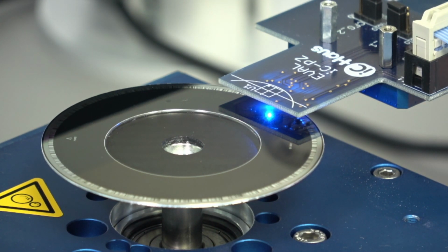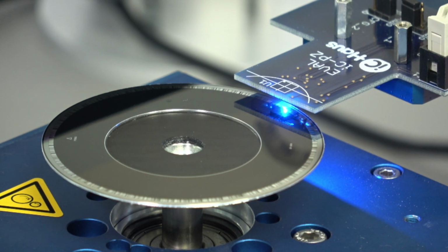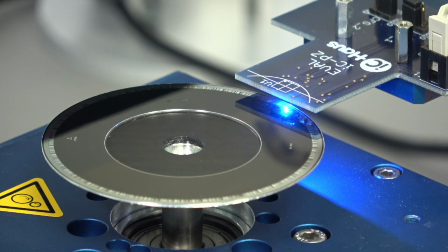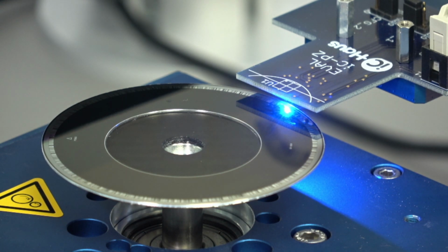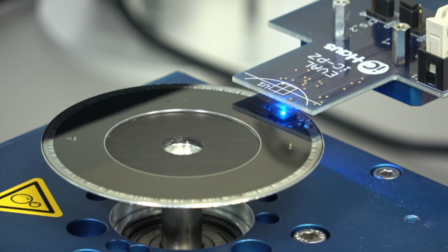And I'd like to show this, and perhaps the cameraman could zoom in. This would be great. So I'm going out a little, and as you can hopefully see, the LED is driven quite high. It's shining very bright blue. And if I'm going above the code disk and getting a signal, okay, the LED will be regulated. So this is a very good indicator to know if there's some signal on my photodiodes or not.